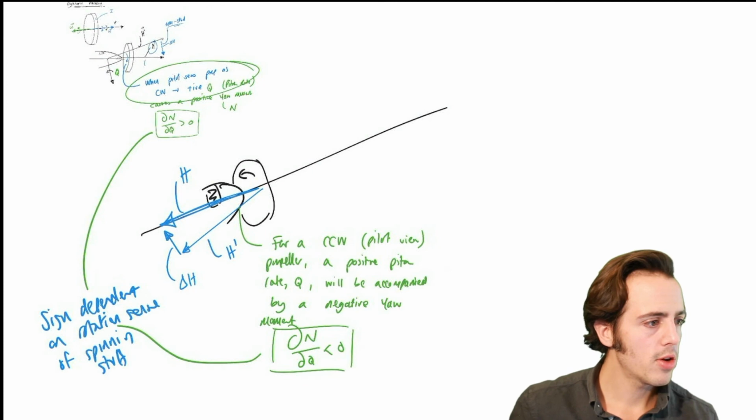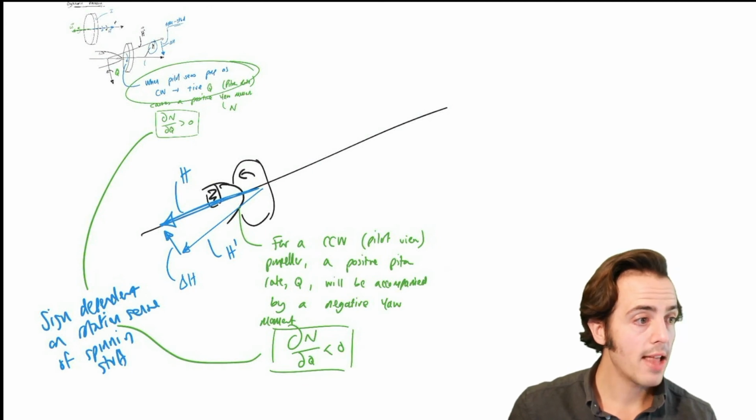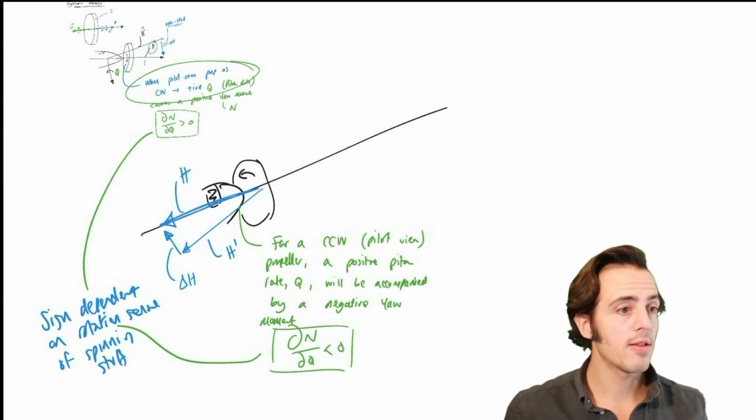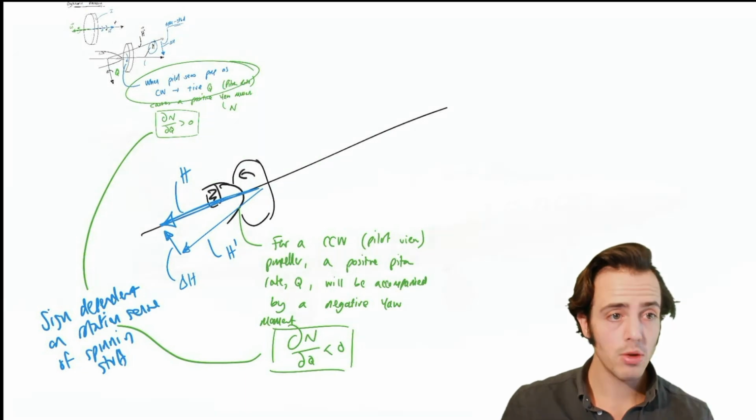Okay, so we've gone to the end of this static stability module. We've introduced the ideas of trim and static stability, and the concept of stability derivatives, and we've shown them in three different formats: dimensional, coefficient, and then the non-dimensional coefficient forms. So the way I want you to think about these derivatives is to be able to relate them to the stability of the aircraft.